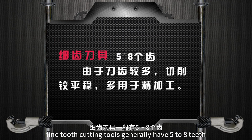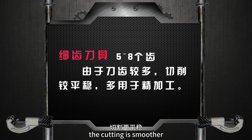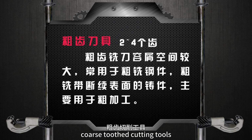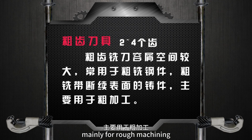Fine-toothed cutting tools generally have 5 to 8 teeth, and due to the large number of teeth, the cutting is smoother, so it's more commonly used for precision machining. Coarse-toothed cutting tools generally have 2 to 4 teeth, having a large chip space, so they are commonly used for rough milling of steel parts and castings with intermittent surfaces, mainly for rough machining.